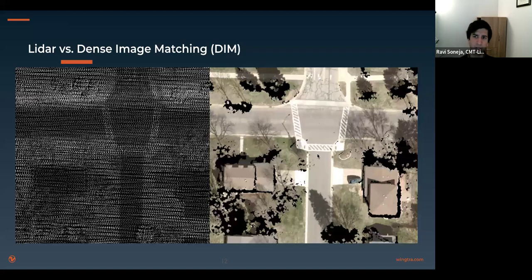I do want to also say, with LiDAR acquisition, that sensor is not talking to the base station. The sensor is running in flight, it's collecting its own GNSS data, and the base station data is used in post-processing to correct the trajectory.